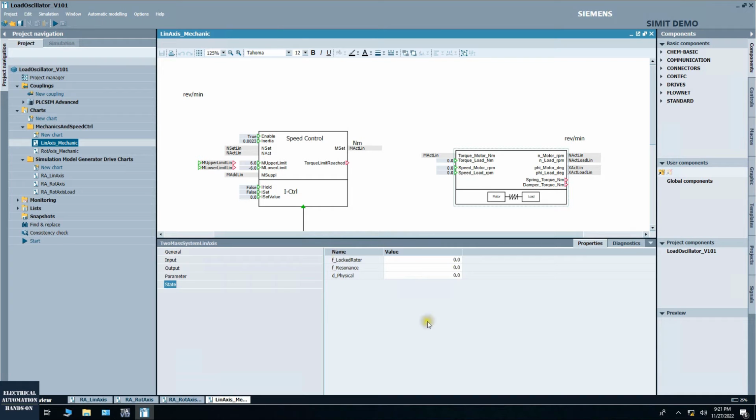So the system will automatically calculate, especially this frequency for the resonance. The reason why the system has oscillation, that's because when your drive system and your load system, their frequency, they are similar. Especially when your drive system approach to the resonance of your load frequency, then the system will show the vibration. We will see the calculation result at here. Well, it is online. So this function block is mainly used to simulate two mass system, the real load, that behavior.